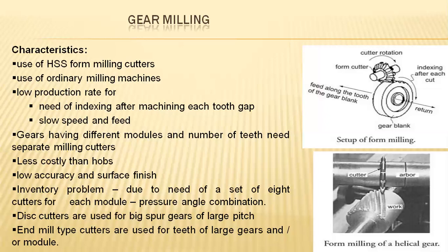Even this disc cutters are utilized for big spur gears, which are having large pitch diameters. Nominally, end mill cutters are used or preferable for teeth of large gears or modules.